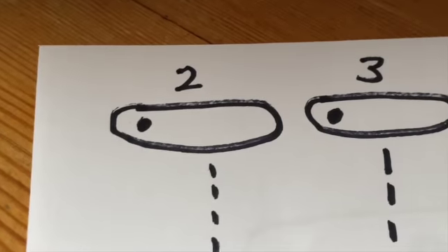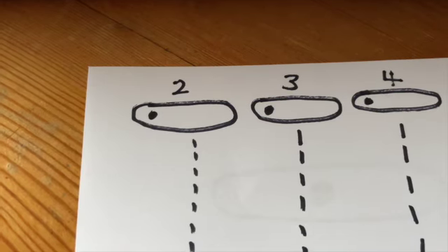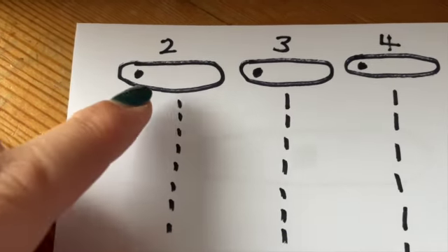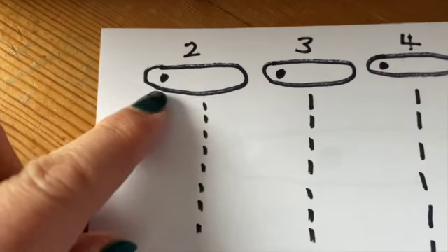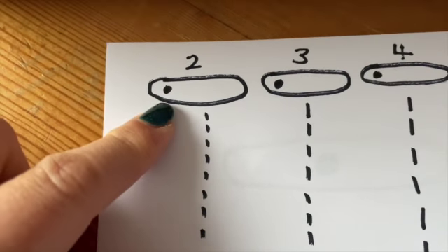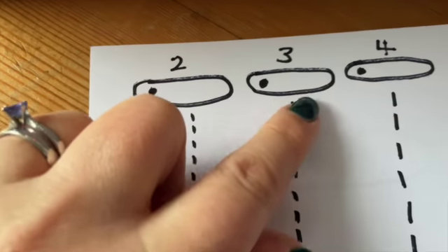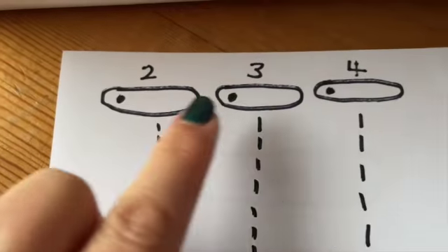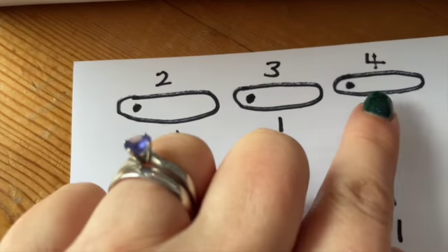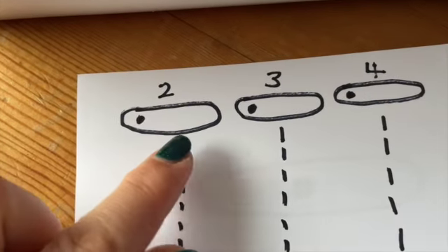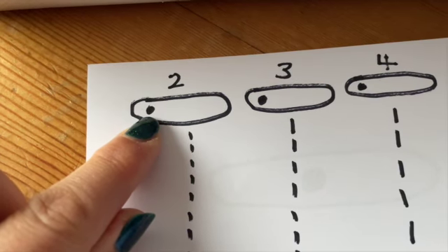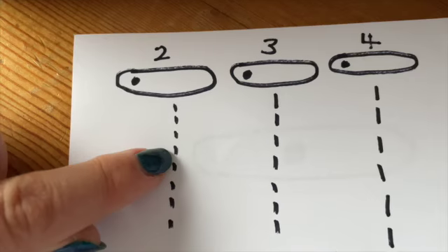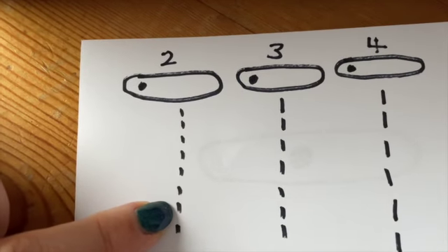So if you have a mechanical machine, let me zoom out, you will probably find you've got a dial with various stitches on it, or various symbols. So you'll have a little oval with a dot on the left, another little oval, another little oval. You might have a couple more as well with this dot in various positions. So that is exactly the same thing. It is where the needle is positioned, which is over on the left. And these little dots below it show you your stitch length.